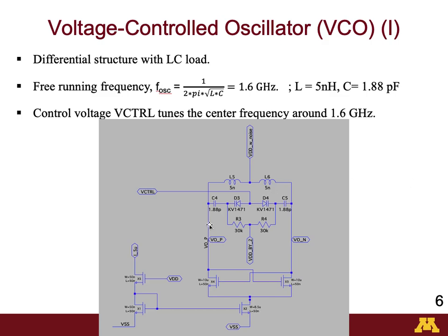On the bottom, the cross-coupled NMOS pair creates positive feedback which oscillates. However, in a SPICE simulation, unlike in the real world where there is plenty of noise coming from resistance and wiring resistance, etc., the simulation is ideal. We don't have that. So we have to artificially inject an additional noise source to trigger this oscillation initially, which we supply from the VDD side.